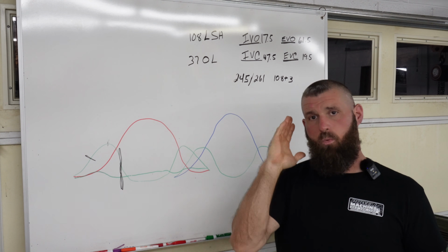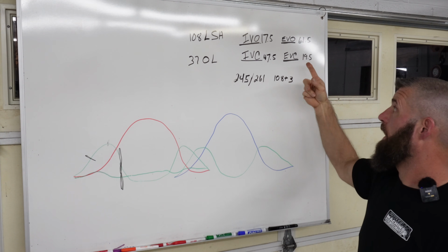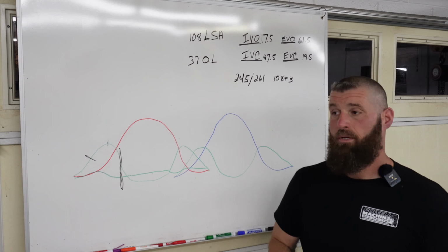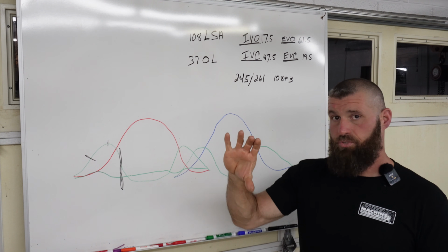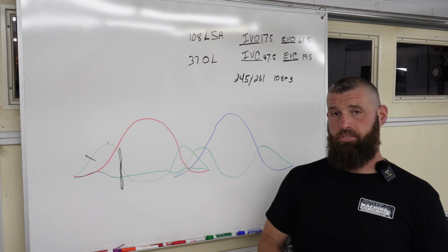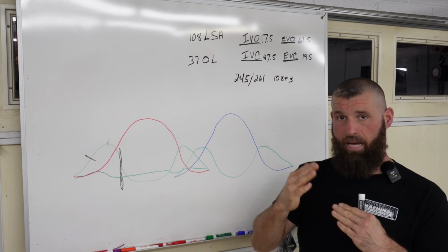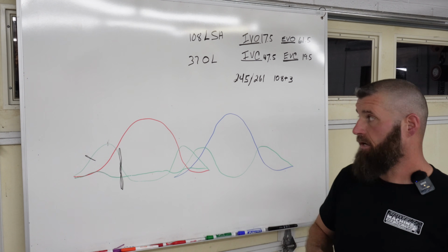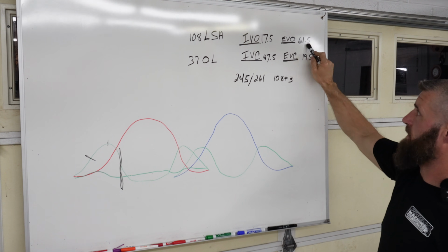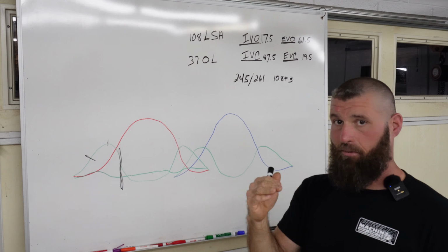So if you just whack the exhaust valve open, the exhaust valve is opening at 61.5 degrees before bottom dead center. So if you just whack the valve open, it's going to knock all the pressure out of the cylinder. So you just rob the power stroke. So you've got to be careful. We want to open this valve as early as humanly possible without murdering the power stroke.